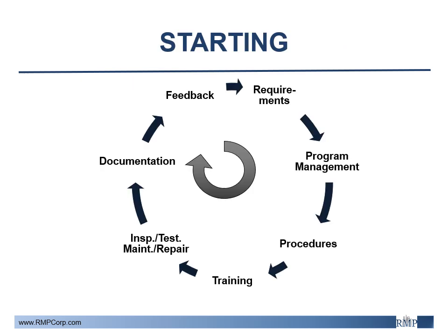There are 7 parts that altogether create an MI program. This consists of creating a system for inspection on intervals using best industry practices according to API, IIAR, or the IOM manuals that come with the equipment. Program management must fall under someone's responsibility.